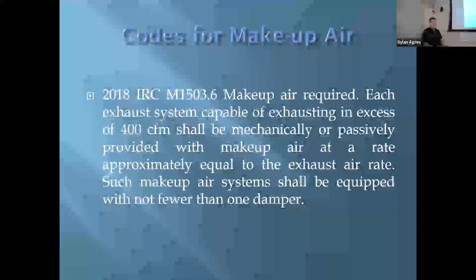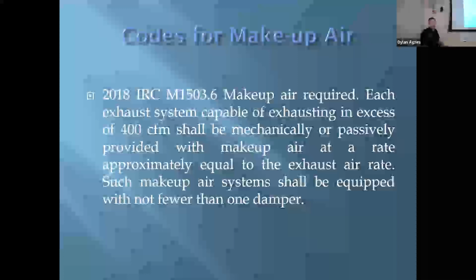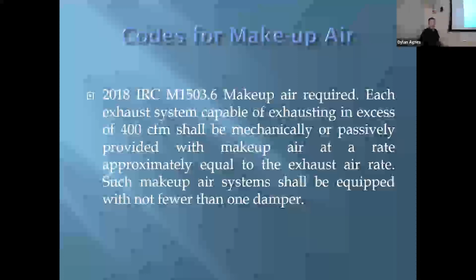They move a ton of air, and they're removing so much air that it's often not conditioned. So they're not fun to work around, but they're out there. I've seen them. 1,200 is not uncommon in some of these bigger homes, but you have to be able to provide makeup air.